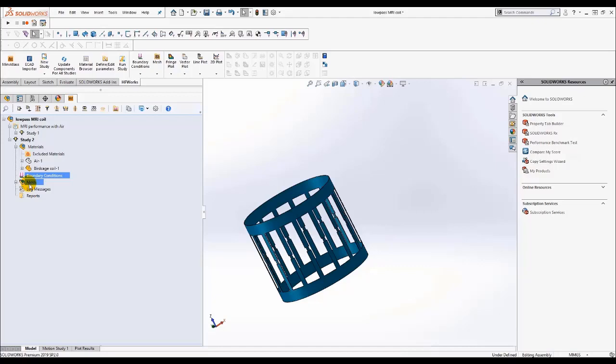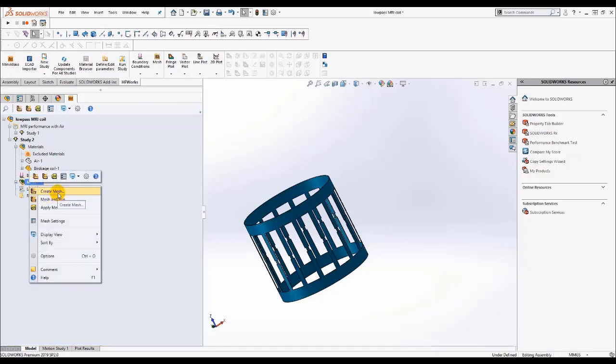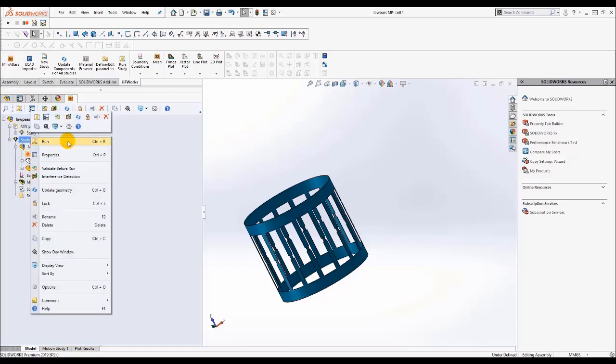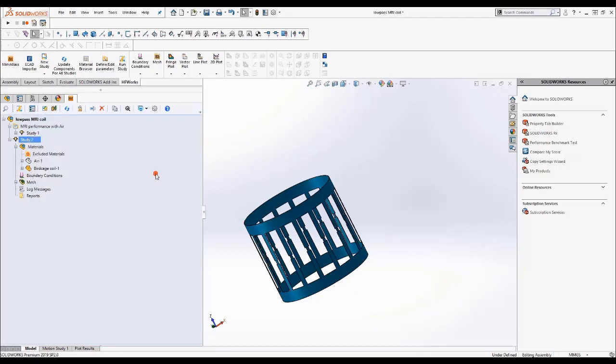And finally, the meshing step. You can create your mesh, the automatic mesh with the default setting, or just add some mesh controls in case of adaptation. Also, you can create your adaptation study based on an existing mesh with user-defined mesh controls. Once all of these steps are done, you just right click and run. For the thermal solution, it is a post-processing analysis, so once the electromagnetic is done, you can create your thermal coupling case with the thermal boundary conditions and solve it separately from your main electromagnetic part.